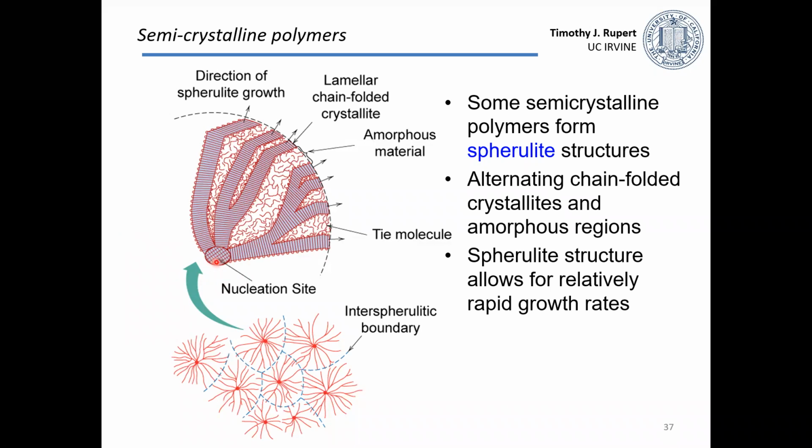We can think of this as a nucleation site for that crystal, similar to how we nucleated crystals of a metallic solid out of the liquid. And those regions that are aligned can grow out just like a crystal grew in metals. But the difference is that in between, there will be regions where these don't match up, and that will be where our material is disordered or amorphous. So we end up with these fingers that are reaching out from that nucleation site.